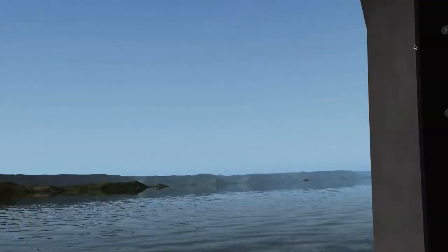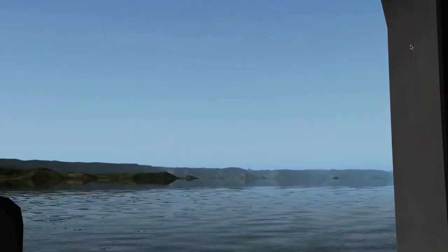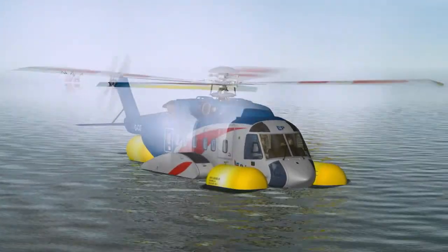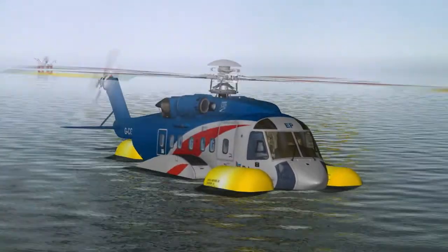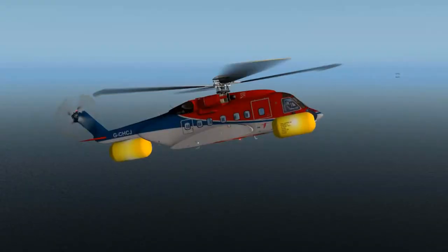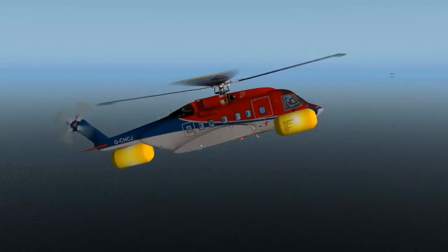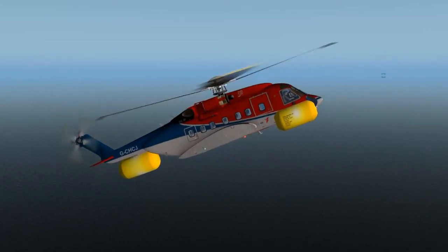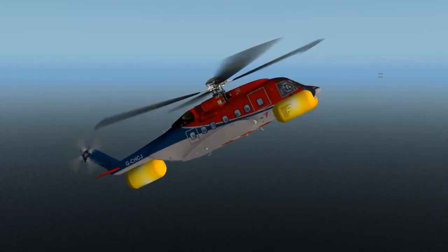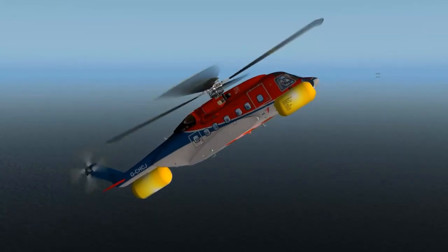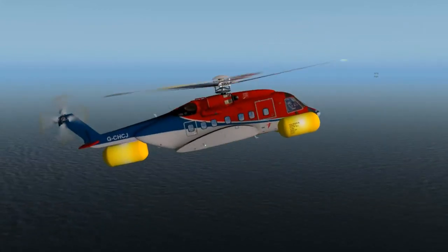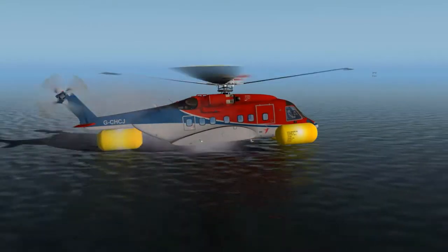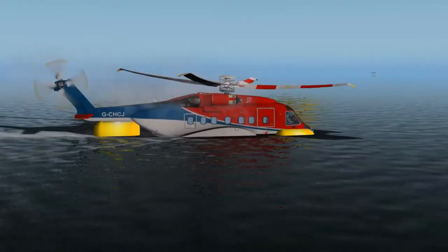So when we reach the point where we're cushioning the landing, we're feathering it with every last remaining bit of lift that we can draw out of the rotor system. You don't want to waste any lift or inertia lingering at a relatively high altitude. So when you complete the flare and you pitch over, hopefully you're somewhere around maybe 30 or even 40 feet above the ground, and you need to let yourself descend.